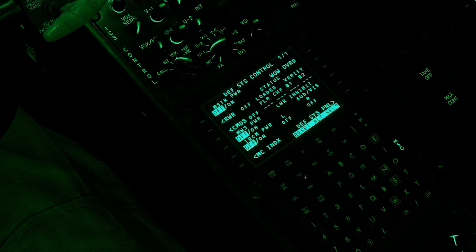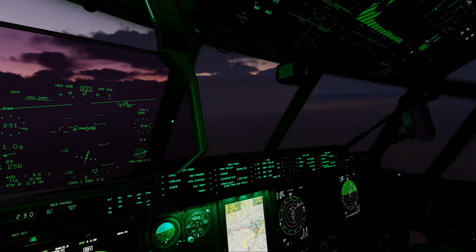Let me bring up the TOLD page here real quick. Looks like we have some precipitation over the city on the north side. Might come in. So I'll be ready on the wipers if need be. Please. And temperature is 21. And barometer, we said 29.33. Alright, got my TOLD data up. Gotcha. So approach, we're looking at about 121 knots, so 120 will do. Okay. Should we get to 120 under 1,000 feet? Yes.